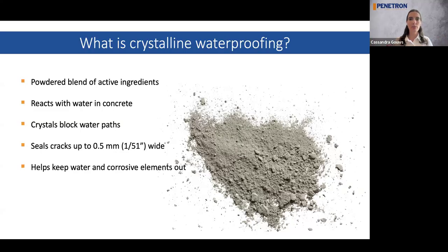And these crystals self-heal and seal all of your little pores, cracks, and capillaries up to 0.5 millimeter in size, which is a 51st of an inch. And those crystals are what decrease the permeability of your concrete, right? So it makes it more dense and it stops liquids from moving through. Now, it's very hard to visualize a 0.5 millimeter, but an average business card thickness is approximately 0.5 millimeter, just so that you know.